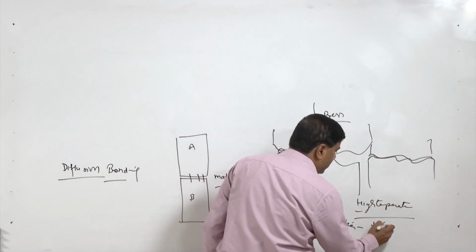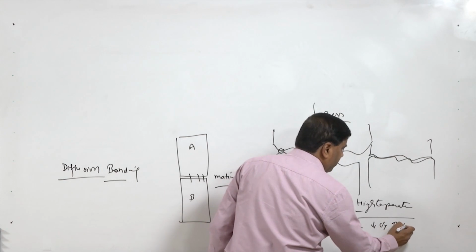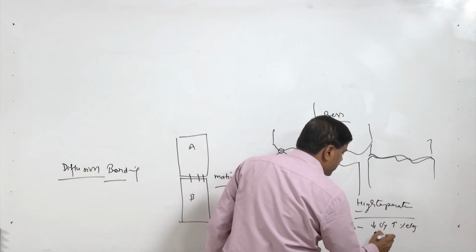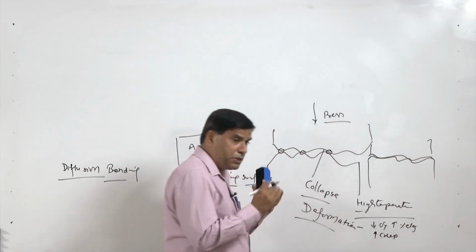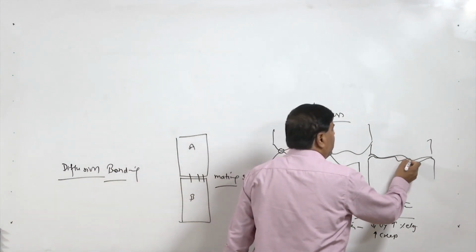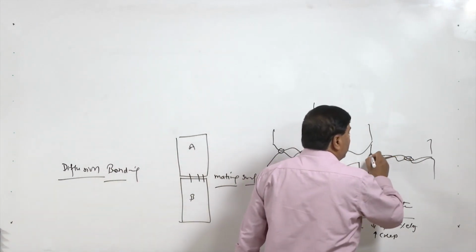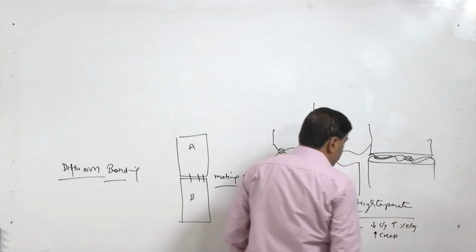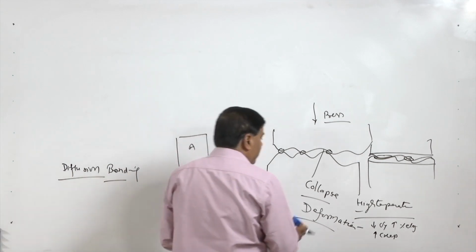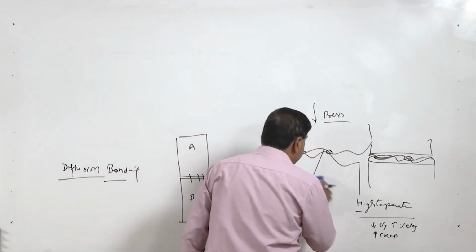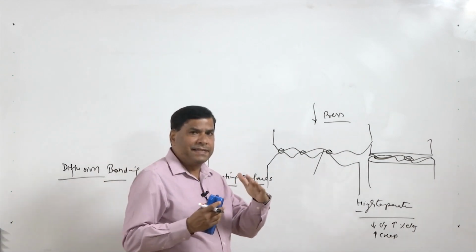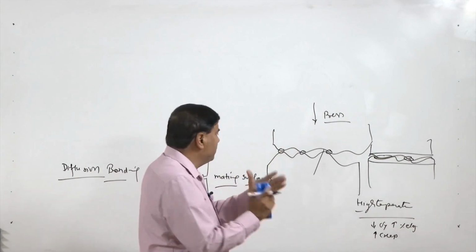One, reduction in yield strength, two, increase in percentage elongation, and the third is increased creep of the material, especially near the contact areas, near the mating surface locations. So, the creep, plastic deformation under the stresses collapses the peaks and valleys, and so the metal to metal contact